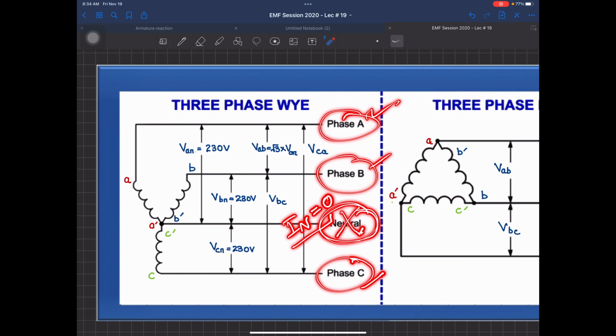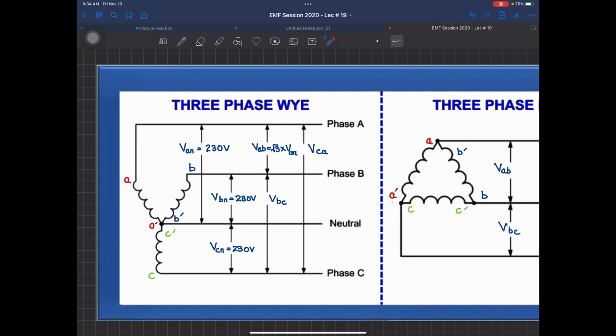But if the machine has a problem in any of the phases, that is, I_A and I_B are the same but I_C is a little different, what is going to happen? There is going to be a neutral current and it's not going to be 0. So 4 wires to your machine are required specifically in those machines which have been running for very long and have developed some fault, because normally any machine can develop a fault with the passage of time. Maybe the bearing is not good, maybe the windings have been damaged a little inside, the inductance is not correct. So either you can have a 3-wire system or a 4-wire system.